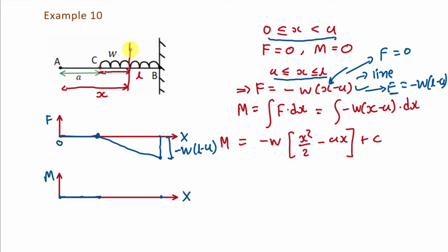Here we apply this distributed load in downward direction. So there will be a reaction at this end which will be in upward direction and which will be the point load. And if you remember, I told you in the notes that the point load gives sudden effect on shear force diagram. So this is that sudden effect on the shear force diagram, which is a vertical line joining these 2 points. Okay. Now we are going to draw the bending moment diagram between this interval.